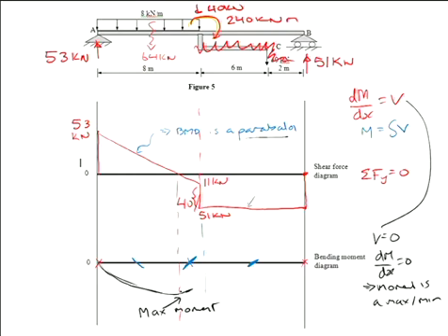So we come up here. How do I know how far to bring it up? Well, we do know that that area there will give me the value of that moment there. And thus, if I add that area on, it doesn't bring it higher. The issue you now face is, does it step up or down? Down. Just memorise it. Clockwise moment, it steps down. We can't put the value in yet, and we know our bending moment is linear and comes up. So you would need to calculate that value and that value there.